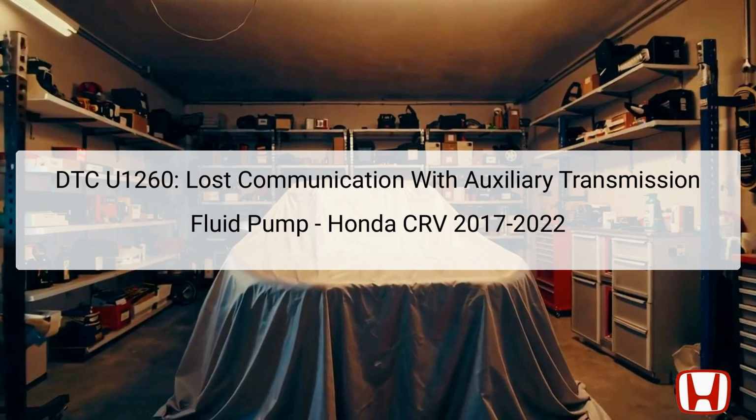When this issue arises, it signifies an electrical fault rather than a mechanical transmission problem. Before proceeding with troubleshooting, it's crucial to ensure that the vehicle is turned on and prepare the Honda Diagnostic System, HDS, to check for any pending or confirmed DTCs as per diagnostic procedures. This presentation will guide you through a comprehensive, step-by-step troubleshooting process to isolate and resolve the U1260 code.